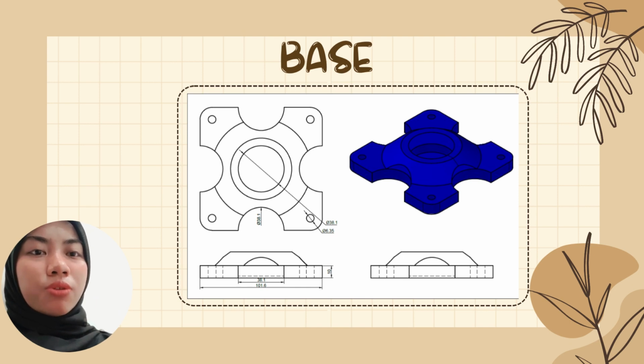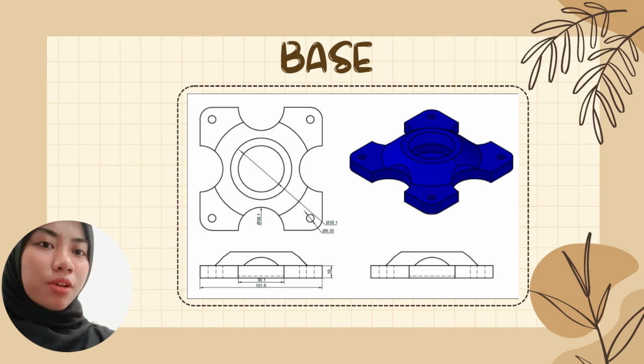After that, we switch to the front view and we create a trapezium for the center with a length of 21.59 mm and a top width of 25.40 mm. Then we revolve the trapezium by 360 degrees by making the center line the axis. After that, we produce 4 circles with a radius of 31.8 mm at the midpoint of each side of the square. Then we use the press tool to produce a hole in the circle.